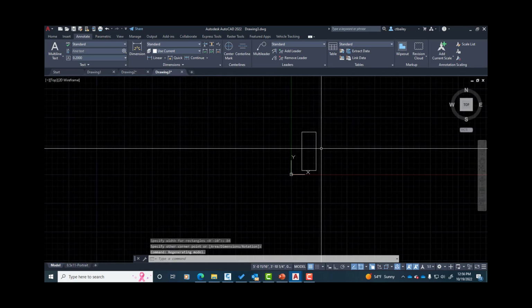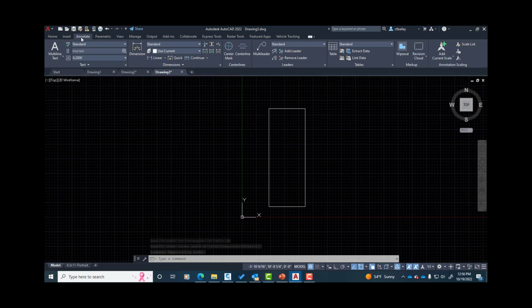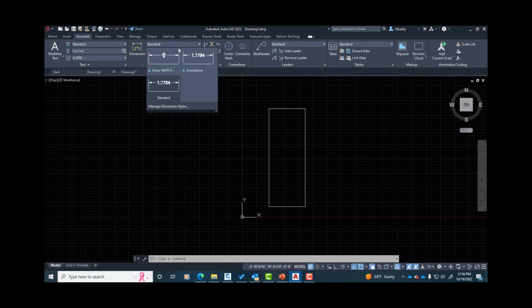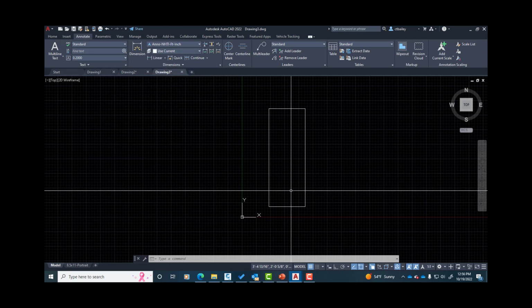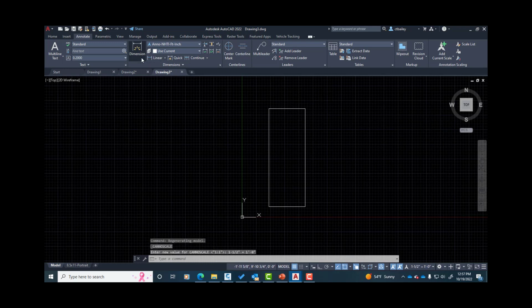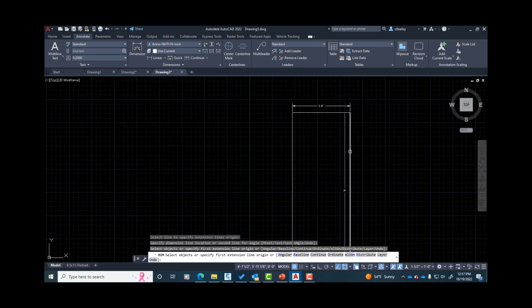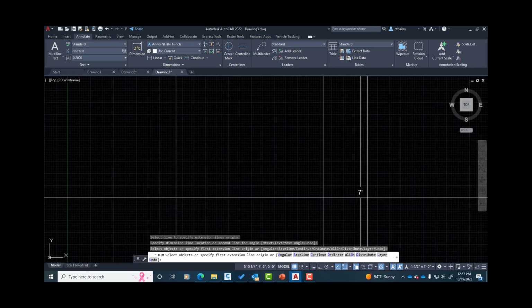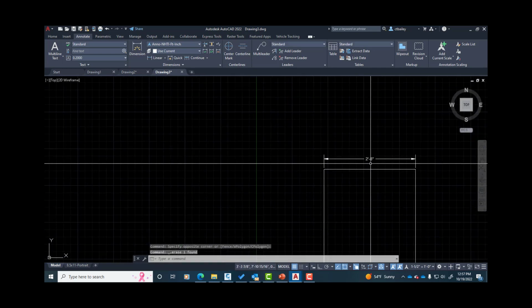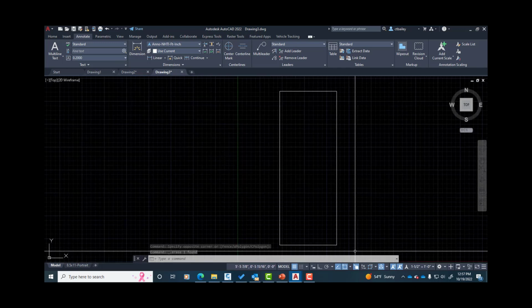Click right there. Alright, so that gives us a rough scale of the door, and let's go ahead and occupy the annotate ribbon here, and let's choose the NHTI annotative, and let's choose an annotative scale, say 1.5 inches equal to foot, and label that right there, 2 foot 8 inches, perfect, and 7 feet, just like I predicted. So get rid of those dimensions there, and now that we have the basis for the door, let's go ahead and create the block.